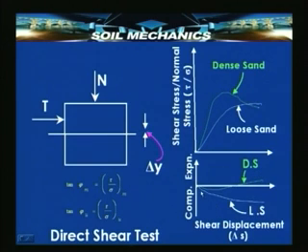On the other hand, it continues to show a compression if it is a loose sand, which means that we will have a peak value of tan phi equal to tau upon sigma peak, or tau upon sigma ultimate corresponding to the portion beyond the peak, and in the case of loose sand only the second aspect will apply.